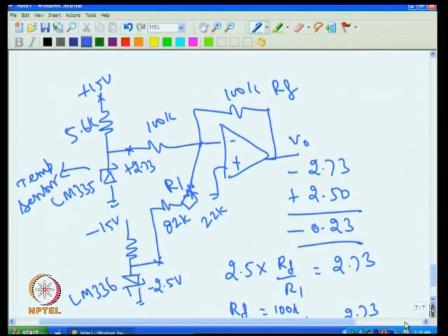So you can adjust this potentiometer. Say I will call this P1, and of course this resistance is R1 here. So you have this resistance we call R1, 82K, and this is P1. So adjusting P1, we can calibrate this instrument, that is, keep this one at ice and adjust P1 to get 0 volt at this point, that represents 0 degree C.